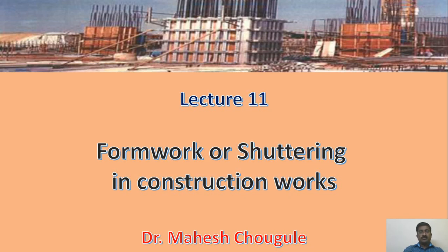Today in this session we are going to discuss the formwork or shuttering in construction works. Friends, as you know, when you are placing concrete in various elements like slabs, columns, beams or other elements as well, it will require this formwork or shuttering, so the shape of that particular component can be maintained, and after the curing period the formwork can be removed safely.